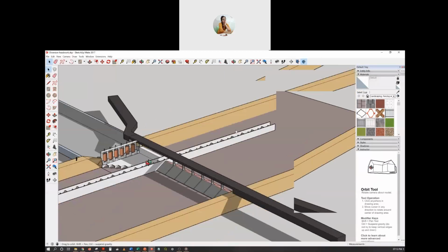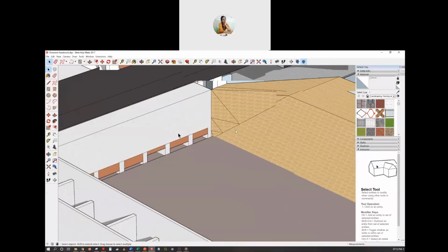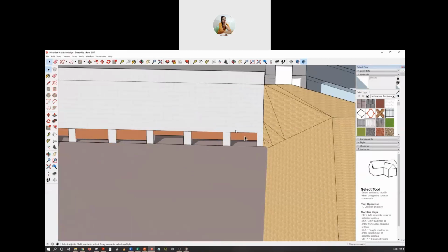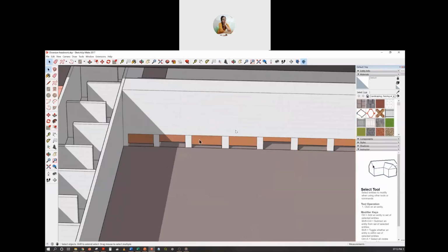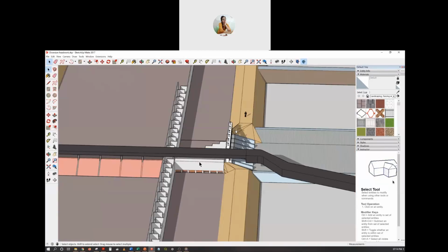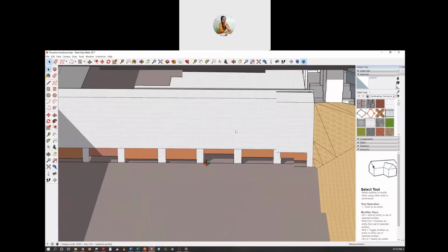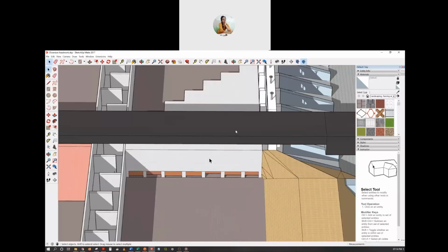Now, there is something else called an undersluice gate. So these undersluices are again gates. So these gates are opened or closed. So these are the gates. These are opened or closed based on need so that water from the upstream can be released to the downstream. Generally, they are not closed together to the complete extent. Only a few of the gates are closed or they are partially opened so that a controlled amount of water is released to the downstream.